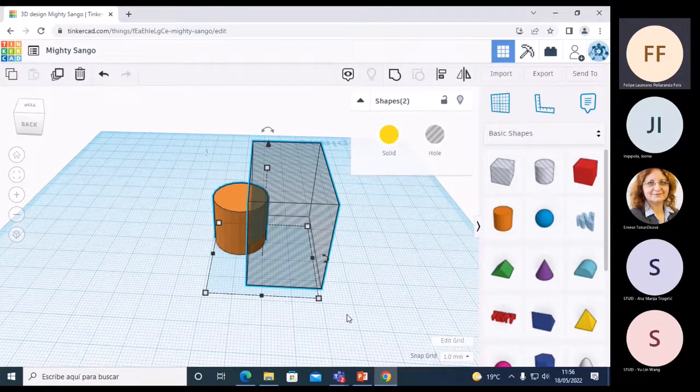And if you check, the selected components have a common border. You see these blue colors around it, and they have a common bounding box, and the base of the bounding box is here. Okay, so they are together. And here on the top, there is a row of icons, and this one is a group. The group creates a union of the objects.